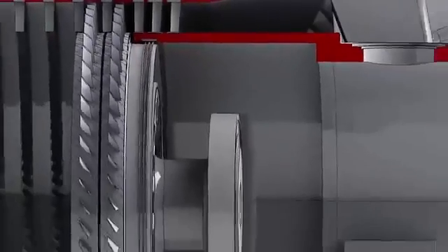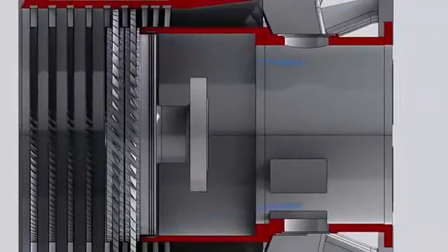The function of this arrangement is to control the amount of compressed air leakage inside the inner barrel. This air, despite being used to cool the first forward wheel space, should be minimized to improve unit efficiency and minimize air leakage inside bearing 2 seals.